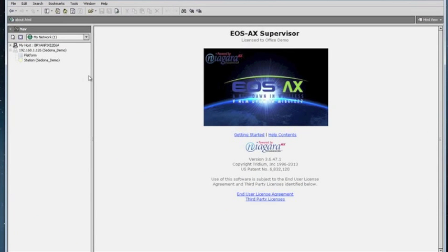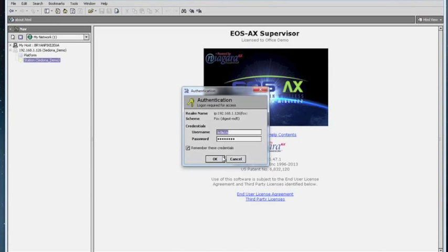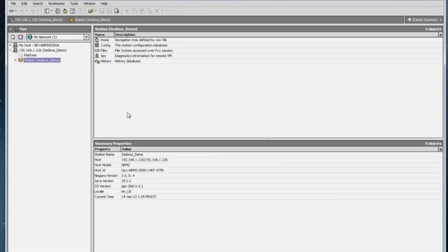Okay, we're going to start from the very beginning and give you guys a demo as to how you would actually set up your Sedona network. From any Niagara-AX workbench version 3.6 or greater, you simply connect to a Jace. We have a Jace in our office that's running a Sedona demo, and we're going to start from setting up the network initially. So we'll go ahead and open up the station that's running on the Jace.